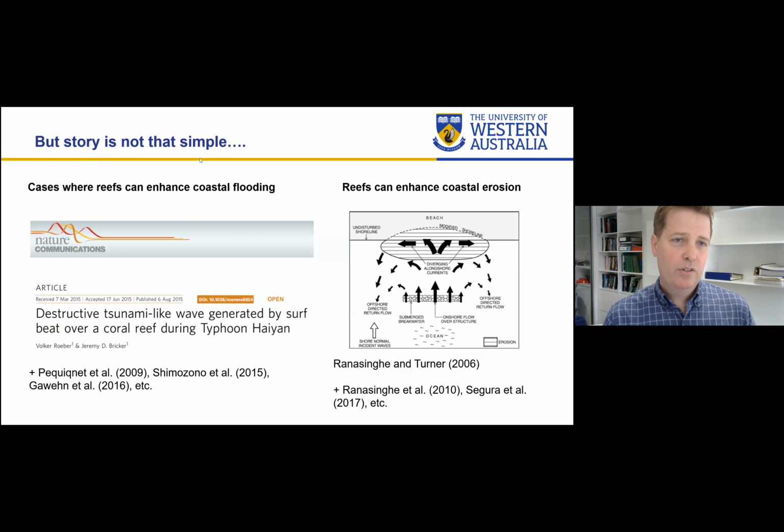So there's a lot of evidence in the literature now where waves can actually cause an enhancement of coastal flooding, particularly at really slowly varying motions like infragravity wave motions, very low frequency motions, and wave setup, which I'll talk about. And so there are cases like in Roi-Namur, where they see really exceptional damage when we excite these kinds of low frequency waves on reefs, and a number of other studies have demonstrated that.